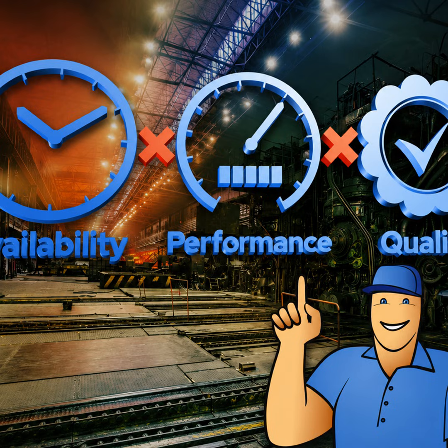The first pillar is availability. Was the machine ready to run? Simply defined, the availability score measures the percentage of scheduled production time during which the equipment was actually running and able to produce product. In other words, when you needed it to run, was it running? This will determine availability losses. This can be determined using one of two calculations. Availability equals runtime divided by planned production time.